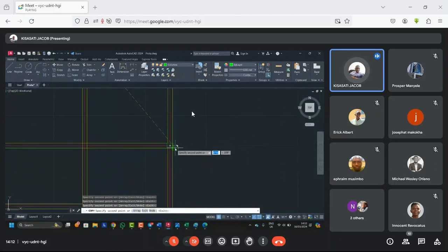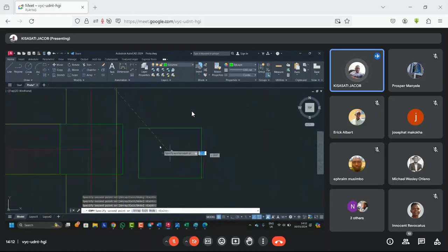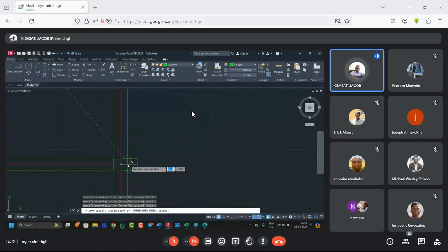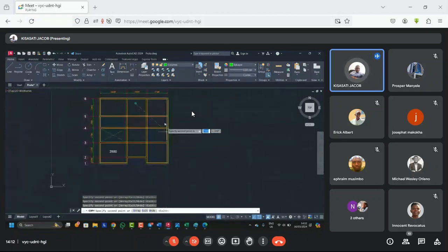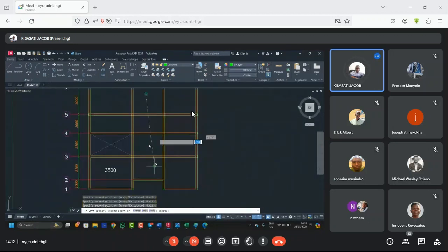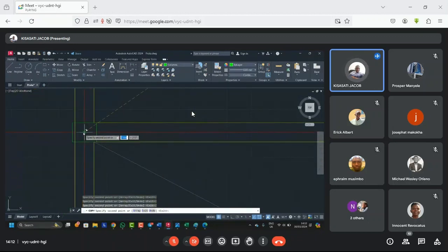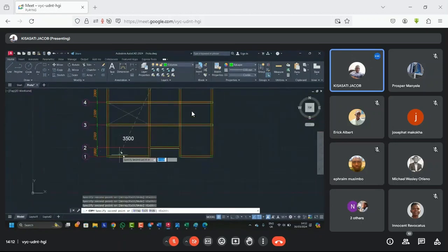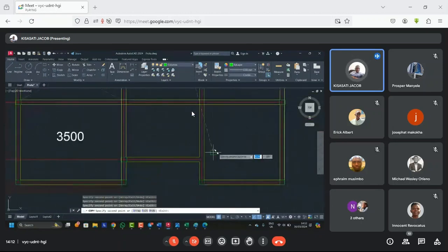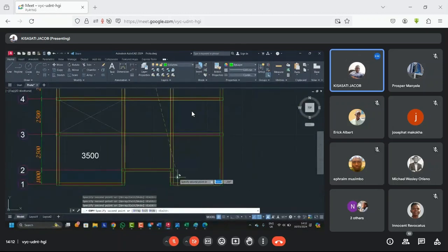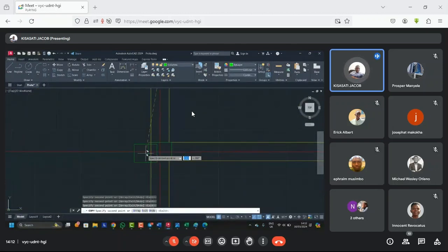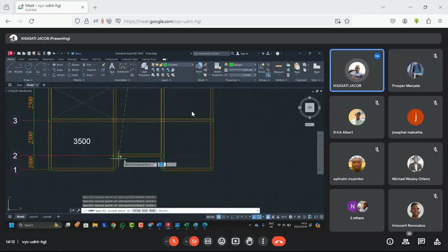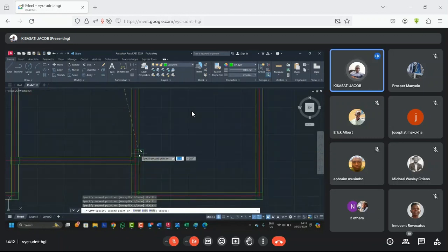Now, what I'm doing is right, because the good practice, we know very well, is that this column has to flush with the beam. But if we do it right now, then it will give us a lot of work in Prota. So I'm trying to avoid that. You will just see what I'm trying to do in Prota Structure. We can also put this one here because it's just a perimeter column, and we will push this column inside to flush with this beam. Then we also push this one inside to flush with that beam.